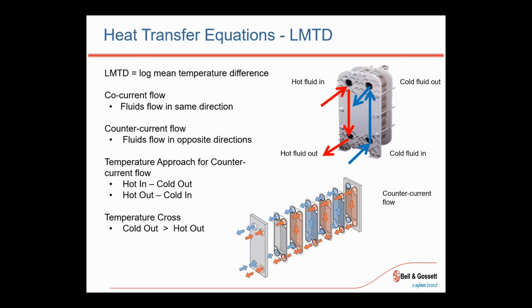On the right-hand side, what you can see is the countercurrent. That's very important with heat transferability, and we'll do an example of that coming up after the log mean example. But the countercurrent's important. And something also that we'll give a visual to is the temperature approach with the countercurrent flow. So where you have your hot in is on the same side as your cold out, and where you have your hot out, you have your cold in. That's going to give us our best heat transfer.